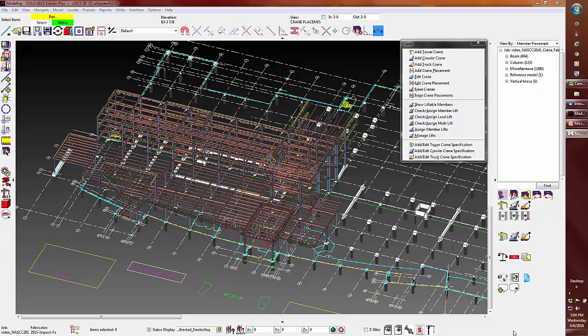Trucks and crawlers can be in and out of the site quicker than a tower crane. Project size and height of structure: high rises, of course, will generally require tower cranes. Availability of cranes: in some cases, you are restricted by the available cranes in that location at the required scheduled time. Available travel space for the crane during erection. Can the crane travel to positions that allow you to set the steel? The soil and terrain of the site.